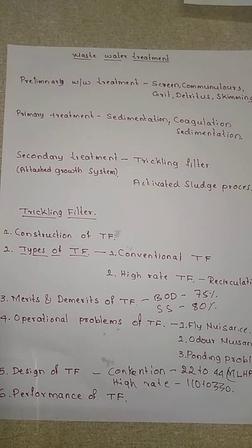Now regarding the performance, as I have told, it has around 75 to 80% BOD removal capacity, and it removes suspended solids up to about 80%. Okay, so this is the brief introduction to the trickling filter.